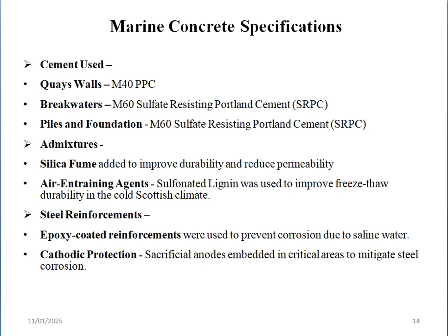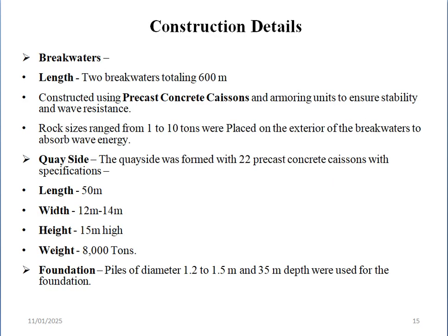Steel reinforcements. Epoxy coated reinforcements were used to prevent corrosion due to saline water. Cathodic protection. Sacrificial anodes embedded in critical areas to mitigate steel corrosion. Construction details. Breakwaters. Length: two breakwaters totaling 600 meter were constructed using precast concrete caissons and armoring units to ensure stability and wave resistance. Rock sizes range from 1 to 10 tons were placed on the exterior of the breakwaters